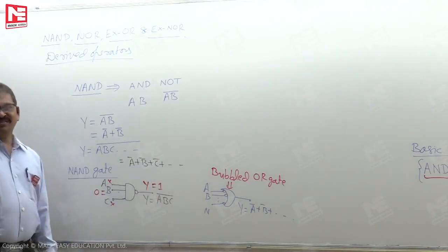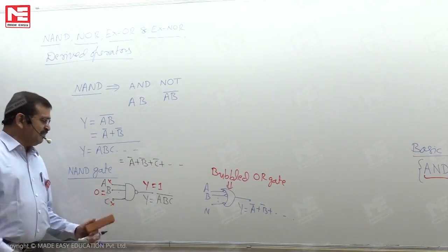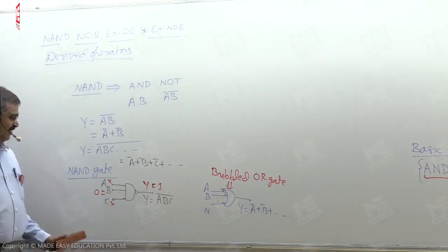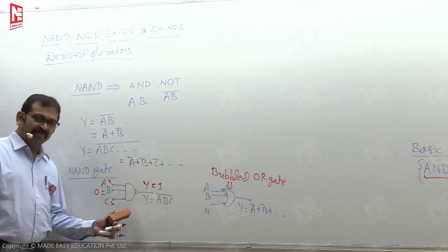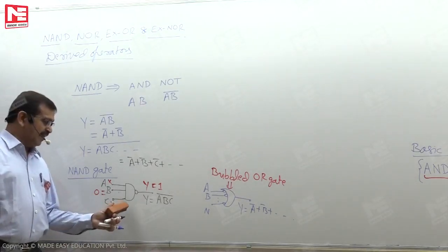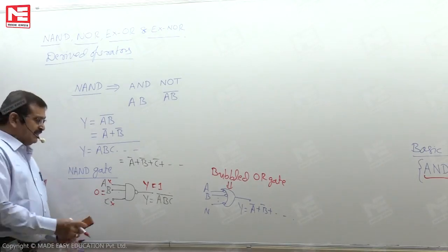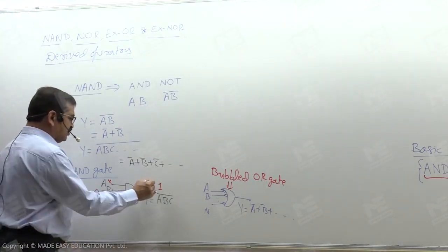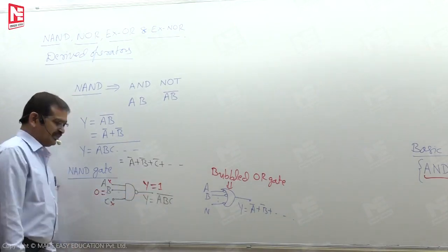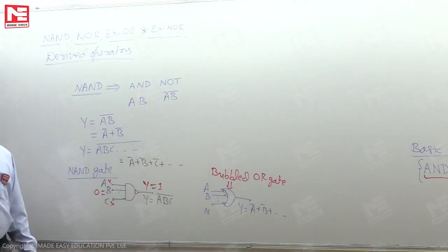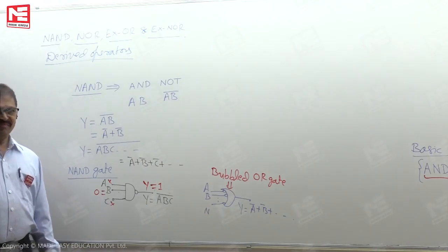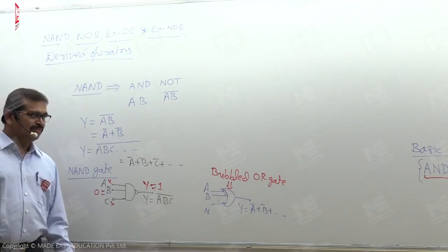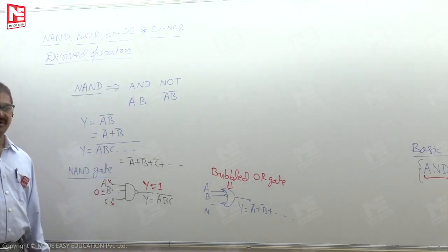So it means A and C variables we are not allowing to pass through this NAND. A and C variables are not passing through this NAND gate. Such input is making the device inactive. Such input is making the device disabled. Based on this, a Boolean constant 0, we must speak, it is the disable input.